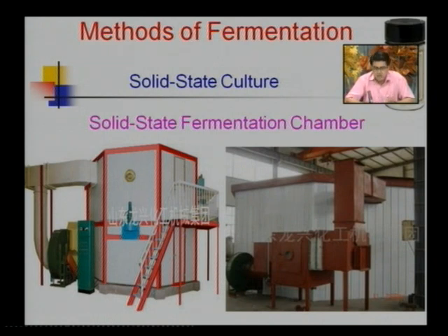The fermenters more commonly employed for citric acid fermentation include a regular stirred tank fermenter or a tower fermenter. The stirred tank fermenter, which is more commonly used at industrial level, accomplishes aeration and agitation with the help of a mechanical agitator and a sparger. Spargers are more commonly employed for aeration purposes.